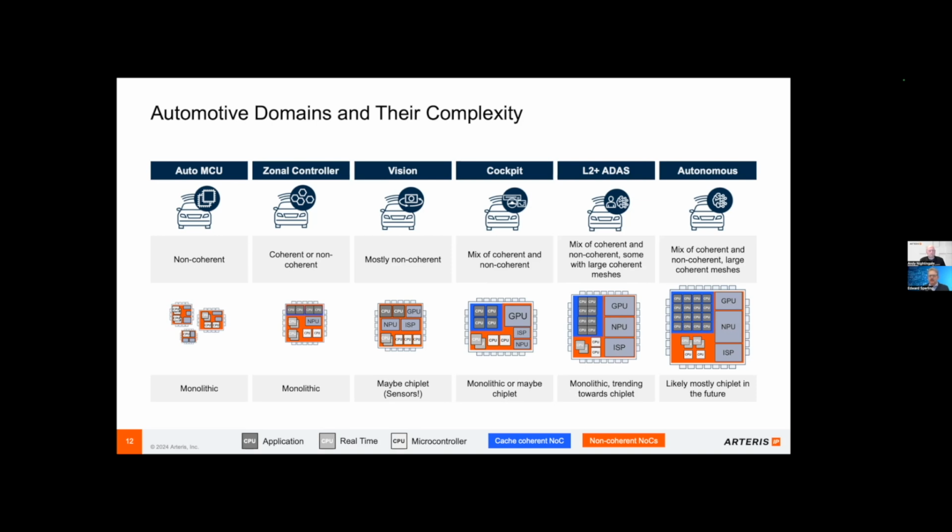And as you start moving further to the right of this slide, you're adding more and more decisions that have to be made in real time, right? So now you're not just taking that data that's coming in from your sensors, you're analyzing it and reacting to it at a ridiculously fast rate. This need for reduced latency obviously puts a burden on the compute resources and the compute power of the system. So it really has to react in real time, from an event that just needs servicing in an arbitrary amount of time to something that really is quite mission critical. As we said, as we go to the right, where we're coming to advanced driver assistance systems, the reactivity just really needs to be spot on, and there's no lag in the system for obvious safety reasons.